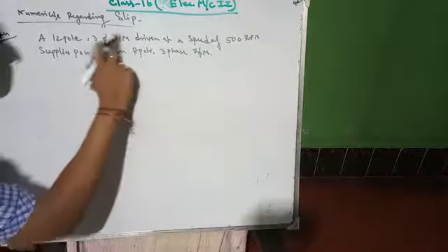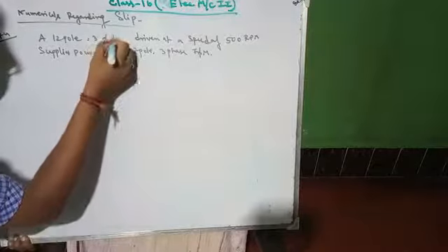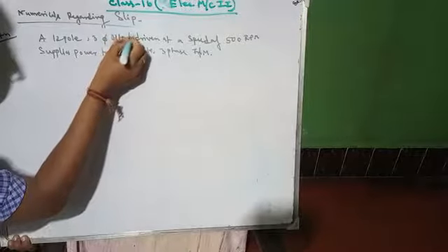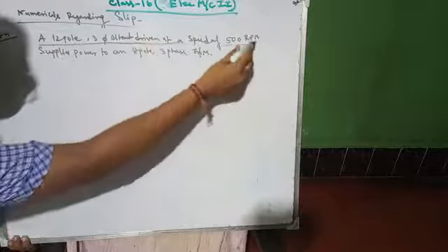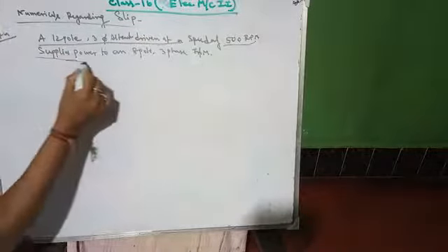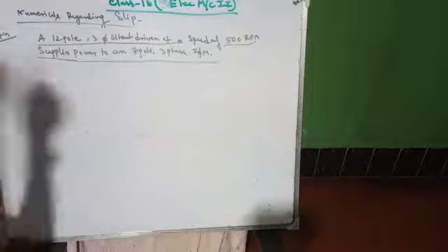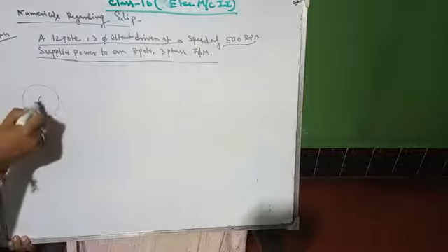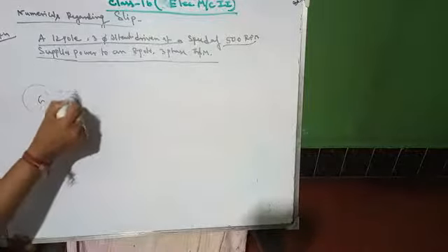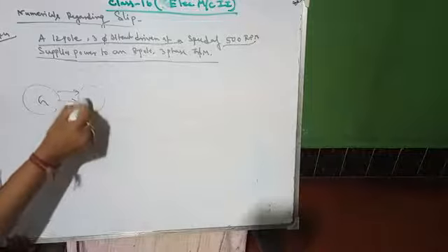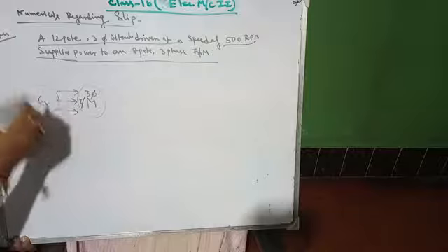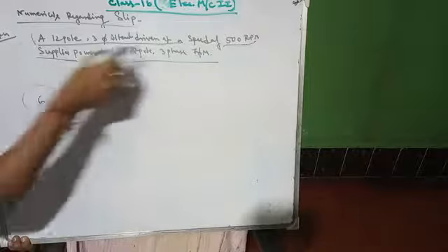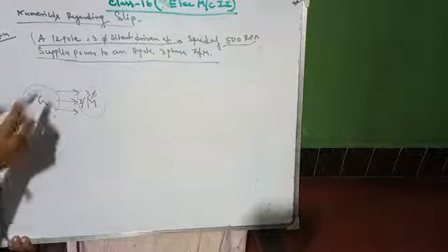Okay, so the first one is not a motor, it is an alternator, right? So this 12 pole 3-phase alternator driven at a speed of 500 rpm supplies power to an 8-pole 3-phase induction motor. That is, a 3-phase generator is supplying a 3-phase induction motor. So the alternator is a supply system.